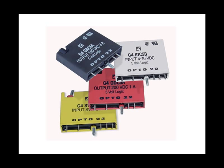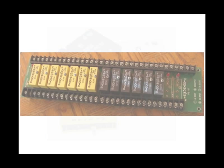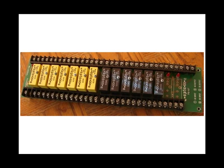These modules can be mixed or matched and inserted into a circuit board that comes in 4, 8, 12, or 16 slots. This allows you to interface a variety of field voltages into the 5 volt DC environment of the controller. This particular example has IAC, so they're input AC, and then they have some output AC. The black ones are output AC, and then there are 2 blank slots.